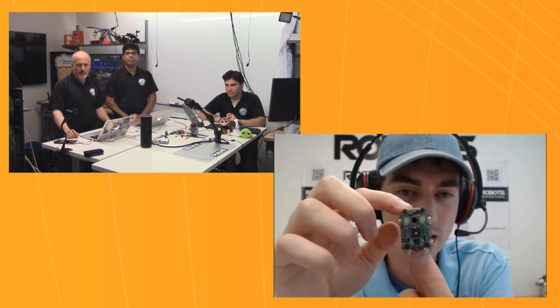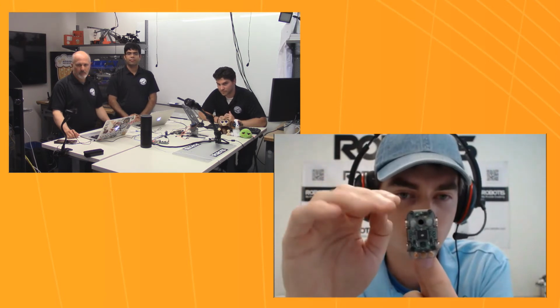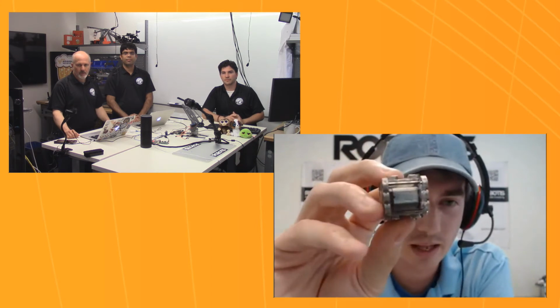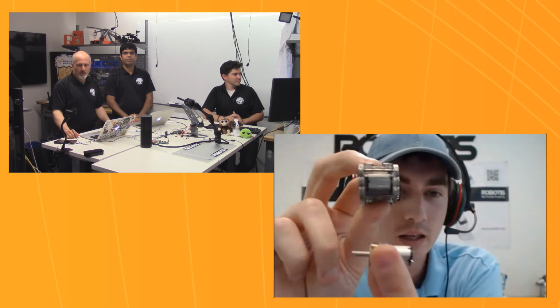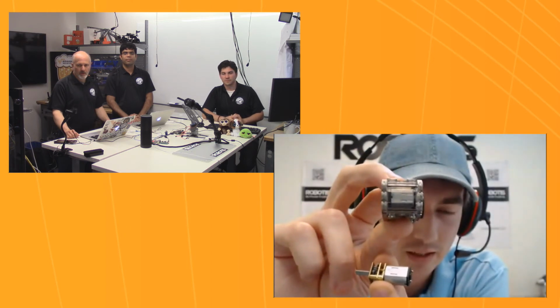So you send it a signal, maybe telling it to go to a 90-degree position. Then it has to figure out where it is in relation to that 90 degrees and how to get there. If it was at 0, it needs to rotate through 90 degrees in the clockwise direction. So the first thing is it sends a power command to that little motor right there, which is really similar to the one I have separate from one of my robots over here. The motor transmits its motion through the gear train.